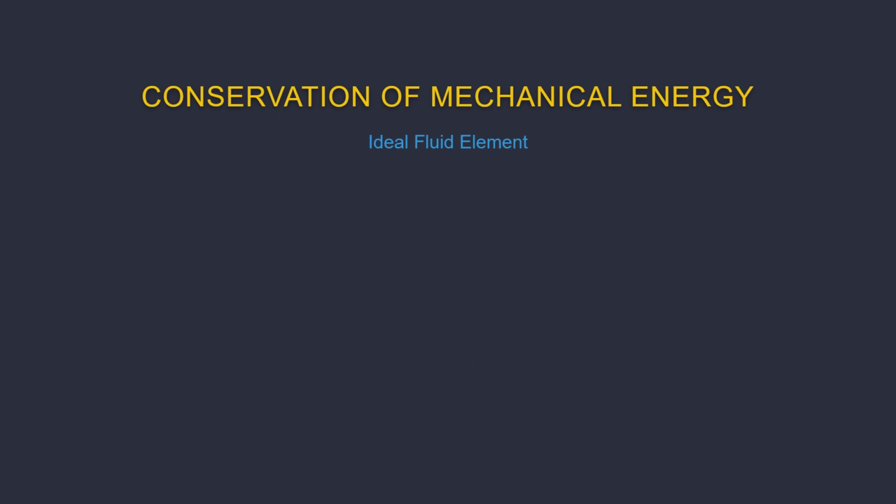Bernoulli's principle is derived directly from the fundamental conservation of mechanical energy applied to an ideal fluid element. This principle requires that the total energy per unit volume of the fluid remains constant along any single streamline. This constancy holds true only when assuming no energy losses occur due to friction, known as viscosity, or due to heat transfer. The total energy comprises three distinct forms.